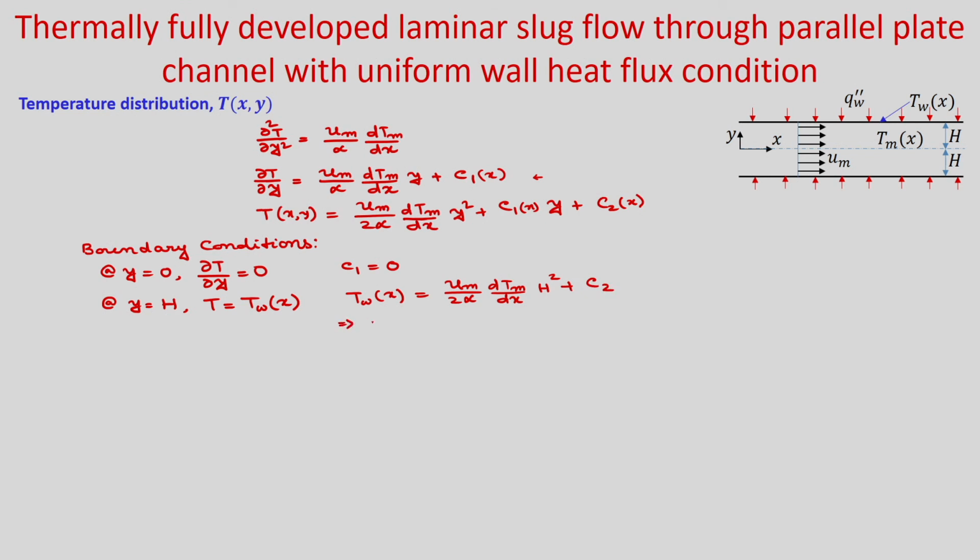Hence your C2, which is a function of x, because T_w is a function of x, will be T_w minus (u_m/2α)(dT_m/dx) h².